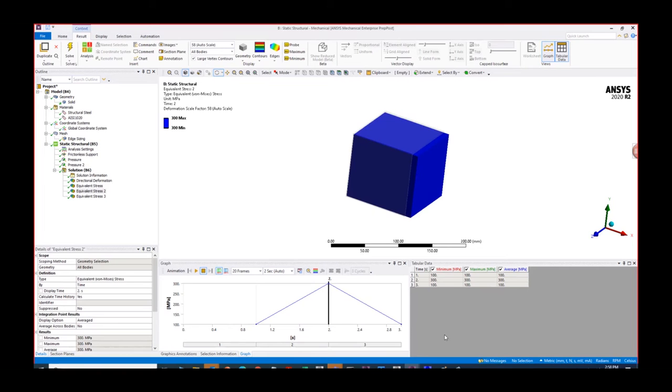So that is why many people, unless it is necessary, or if the induced stress is not crossing the yield, prefer to do an SN analysis. But in that situation, there is nothing wrong in carrying out an EN analysis, even though the stress is well within the yield limit of the material.